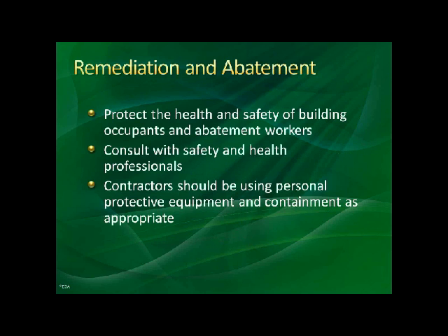A good remediation and abatement is going to protect the health and safety of the occupants. They may want to consult with a health professional before it's done, depending on your client or depending on what they're allergic to. And we also discuss personal protective equipment. You as an inspector need to carry PPE: simple gloves, a half mask respirator, and some goggles or a dust shield for your eyes. Mold can affect you as well.